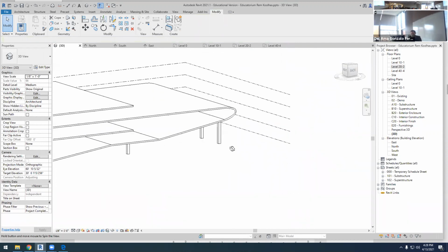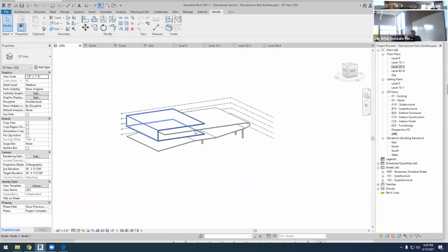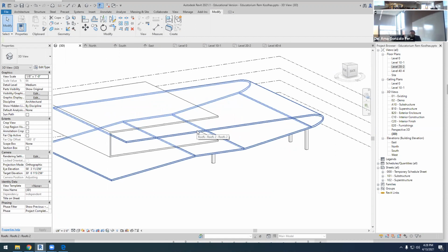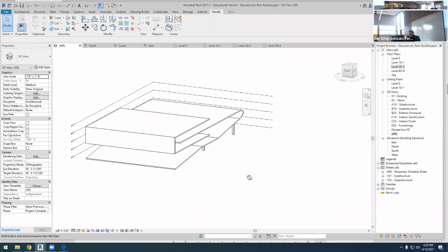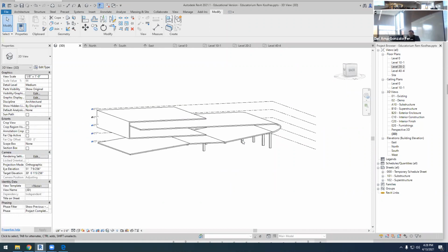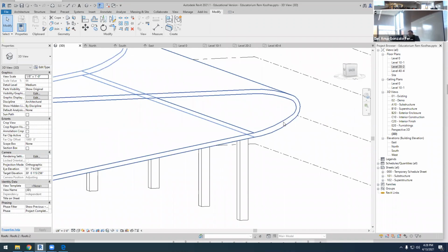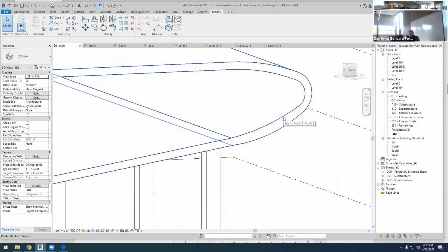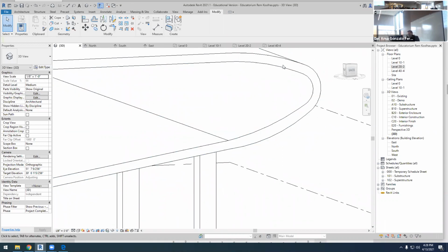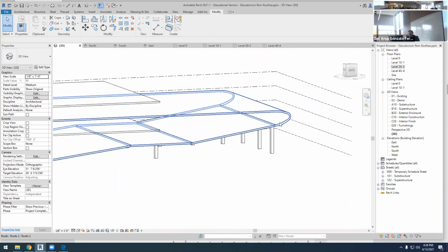Okay, so far you can do this both ways using either a roof by extrusion or architecture component. The result is the same, but since we are going to adapt our curtain wall to that shape, I think the other one was nicer. The other shape was nicer, or probably with a little patience you can do this as nice as the other one.